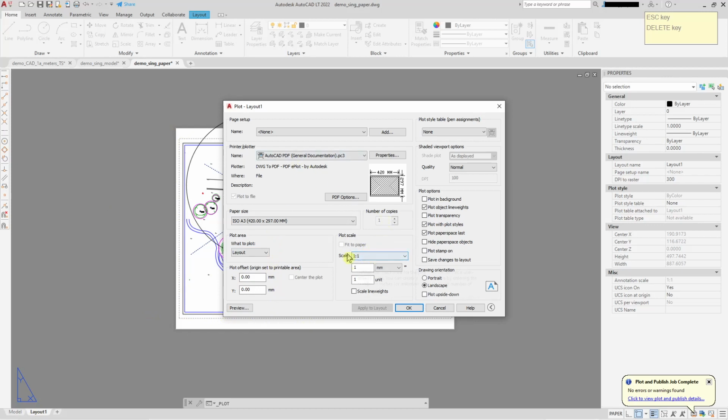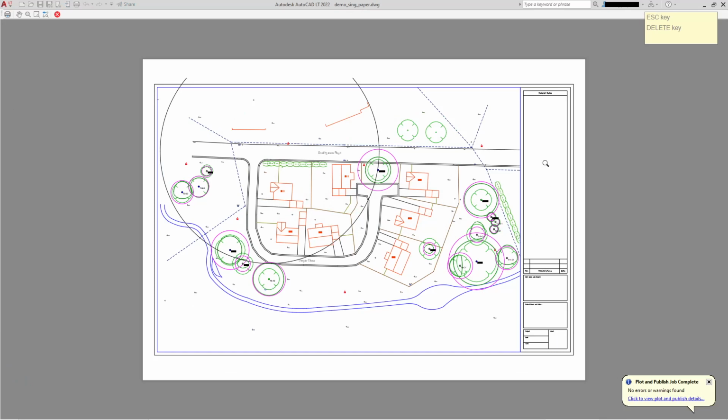And the scale would always be set to 1:1, and it'll be millimeters, because in the UK we're using pages in millimeters. We're not going to deal with inches, so you would set that to millimeters, 1:1, and tick whatever boxes you need, preview it, and you can see this circle I plotted has finished there, where the printable area ends.